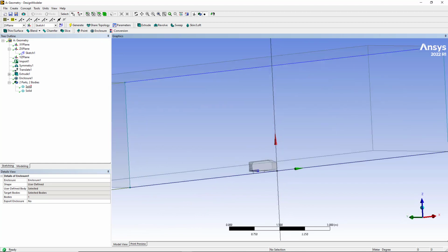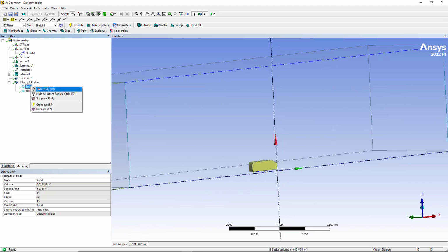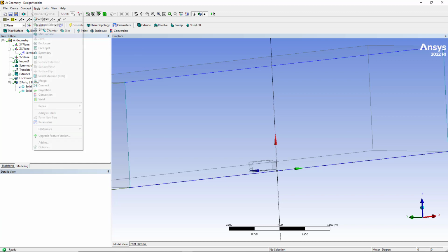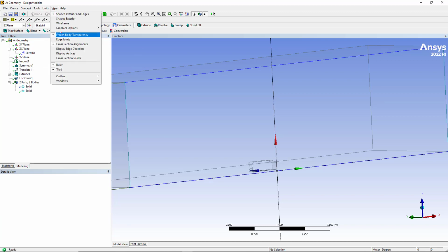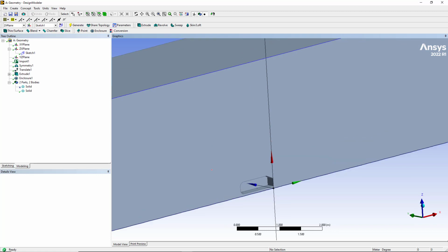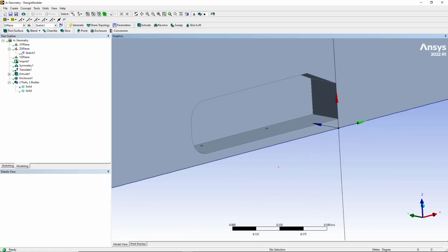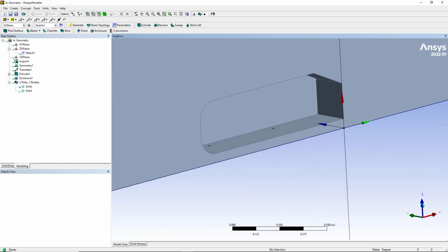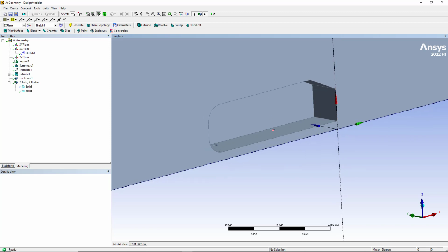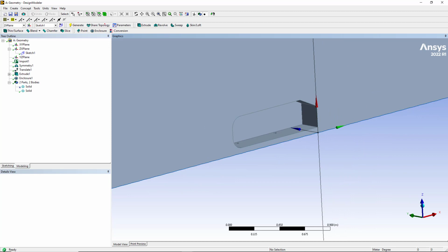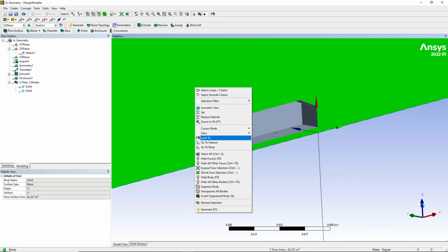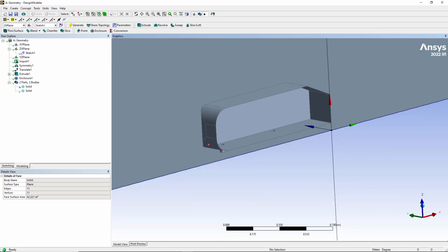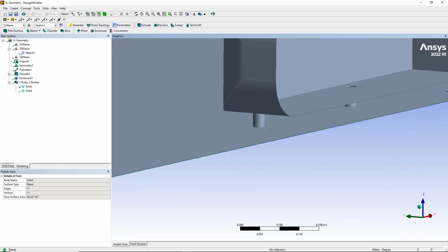Okay, so I'm going to suppress this geometry from here, and then you can turn off the frozen body transparency. You can see that we have the domain. That is the split, after split of the ML body means that the inside of the body is not included, so only the surface body around which the flow will be going over is there. So in this way, basically we made the geometry for this domain. So if you want to hide, you can hide this face, and you can see the things from inside as well.